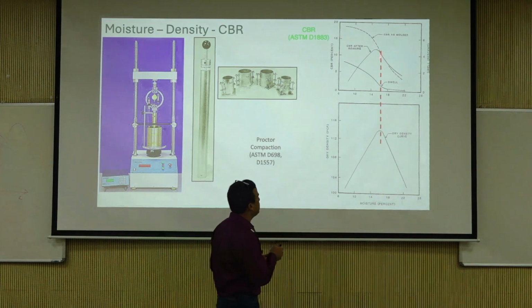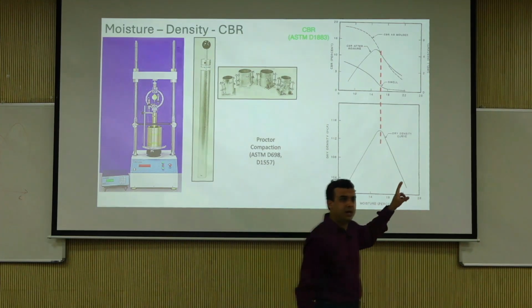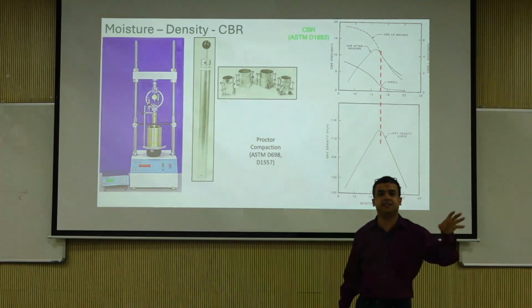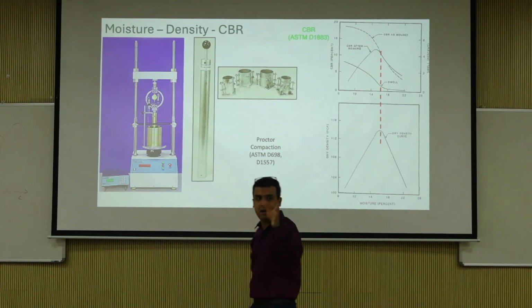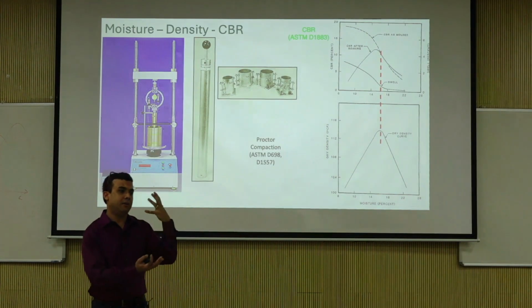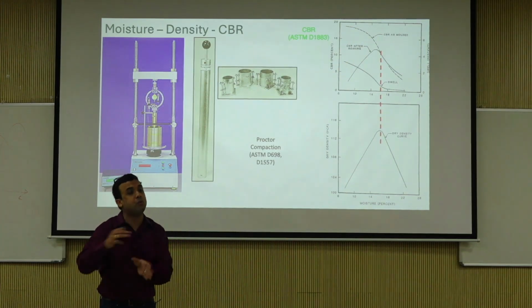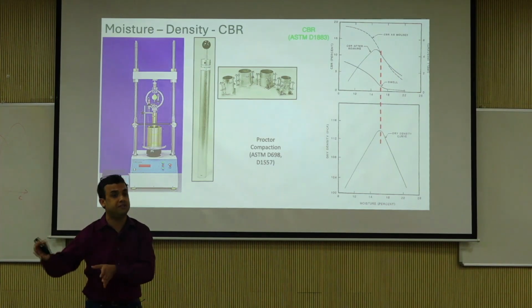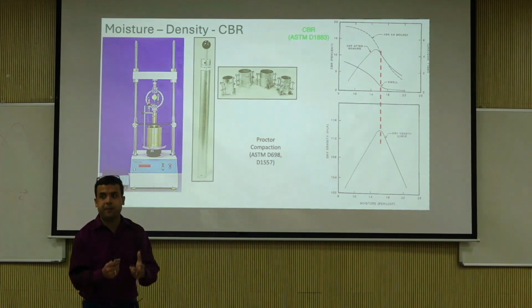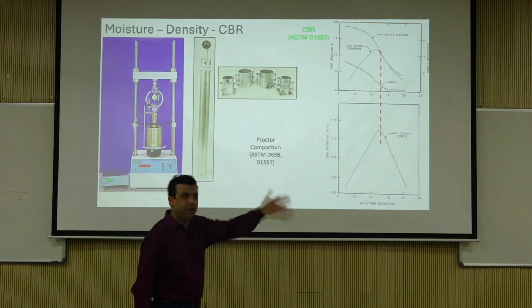But the point is soaking. This is one more thing I wanted to highlight to you: a lot of agencies, when they realized the disadvantage of 96 hours of soaking, move to what is known as unsoaked CBR. They prepare it and test it at that moisture content, the molded moisture content.